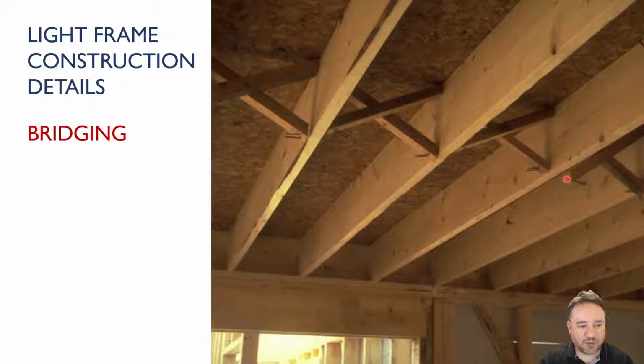This is a detail you've probably seen in your basement before, which is called bridging. If you happen to have a basement and you can actually see the joists, the bridging in between prevents lateral torsional buckling of these beams, which we will talk about in much more detail when we look at bending design for these members.